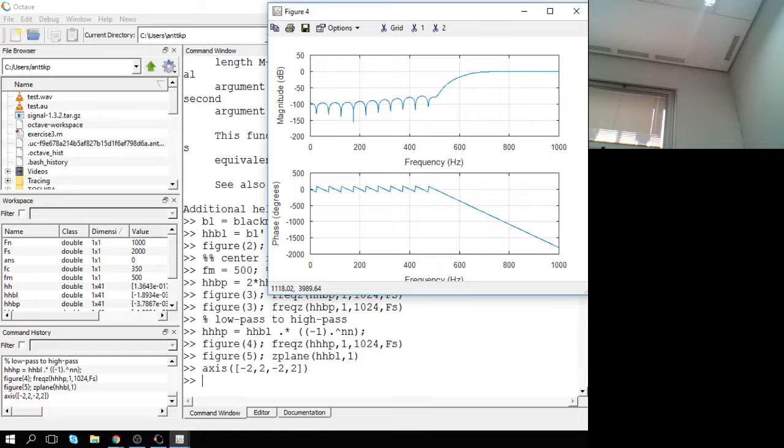And then the implementation of that system is so that you simply have a system which calculates the new impulse response by taking B times the low pass impulse response plus M times the bandpass impulse response plus H times the high pass impulse response, and use this impulse response in a system.